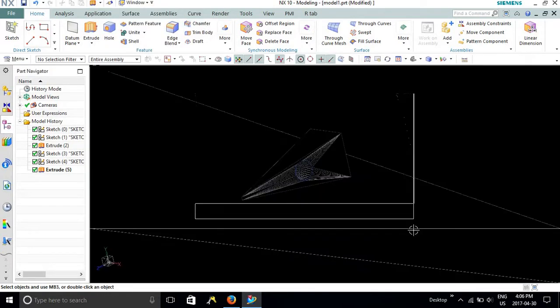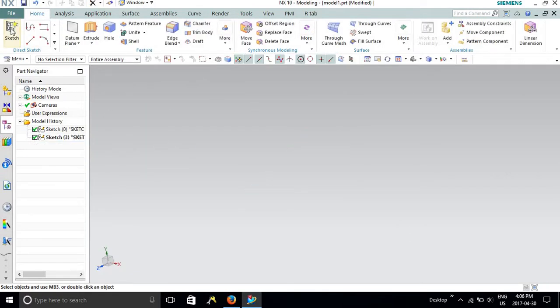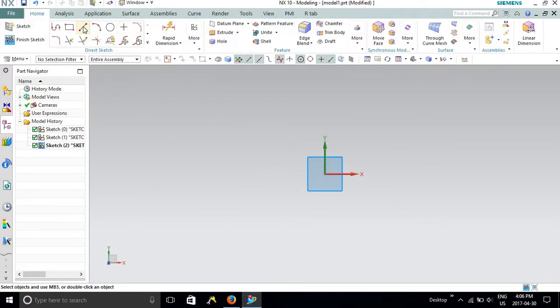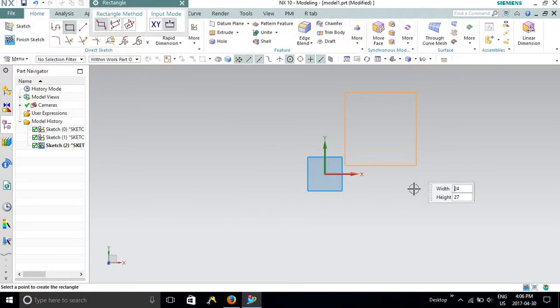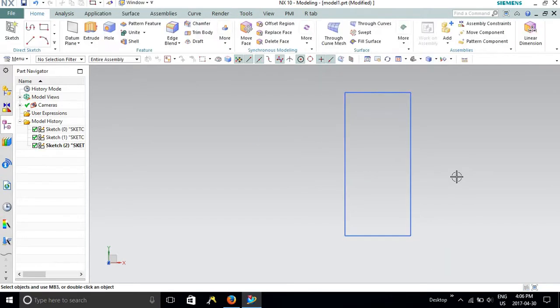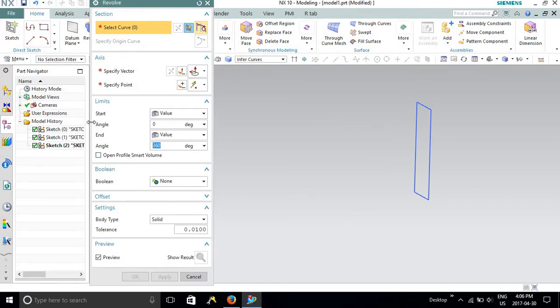And similarly, if you want to revolve, the next option is called revolve. It can be used to revolve a solid portion. It's also similar to extrude, but there we specify in terms of distance, whereas here we are specifying in terms of angles, right?